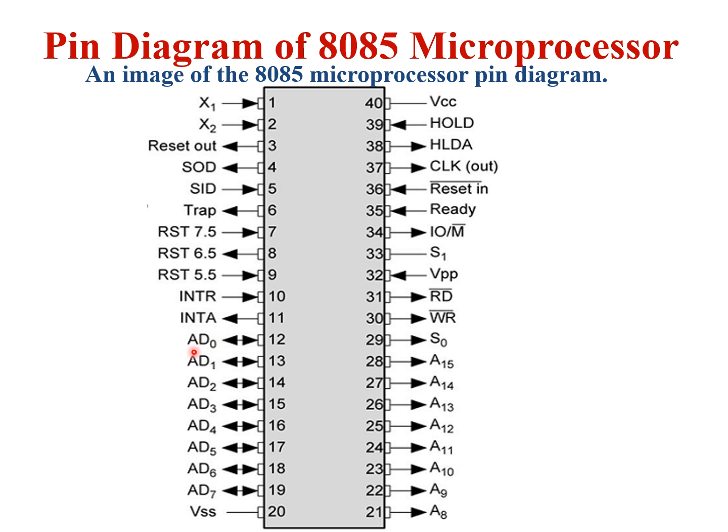Here you can see some of the pins are labeled as AD0, AD1, AD2 in this way up to AD7. Similarly A8, A9 up to A15. These 16 pins are used for carrying address or data, and AD0 to AD7 are used for holding data or address.